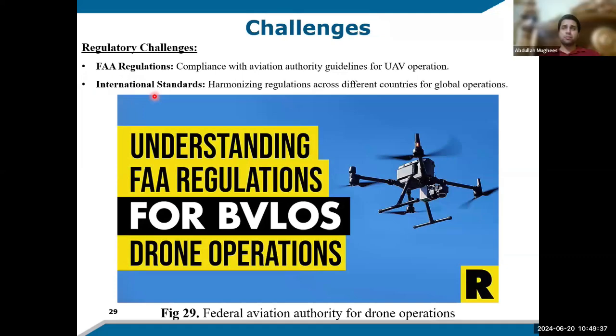Okay, so previously, in the battery slide, I told you that the drones require huge amounts of power. Again, I should mention that I'm talking about multi-rotors. With multi-rotors, if you use solar cells, the area available for the solar cells is not that much, and if you make the body from solar cells, the generated energy will be so little that it cannot be directly used.